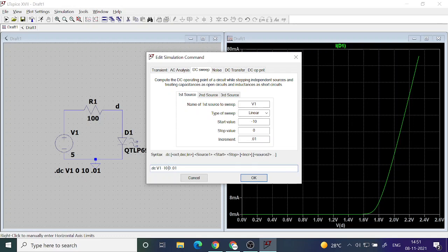Either we give 0 volt or say 5 volt in series with the resistance. Just like you learned in the digital 7 segment display, I told you under each segment there is an LED. So when you give a 0, you are giving 0 volt if it is a common cathode type. If you give 5 volt, that corresponds to 1, you give 5 volt in series with the resistance. So that will make it have a voltage greater than 1.6